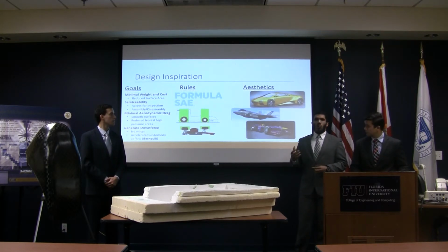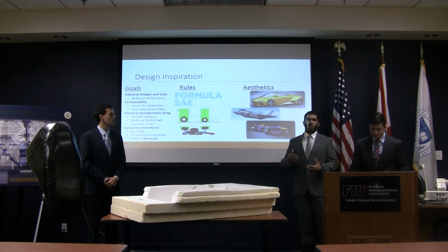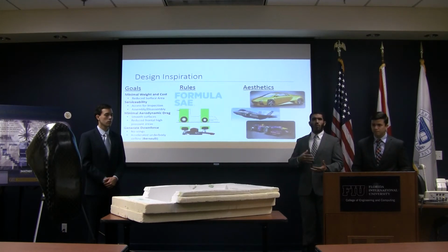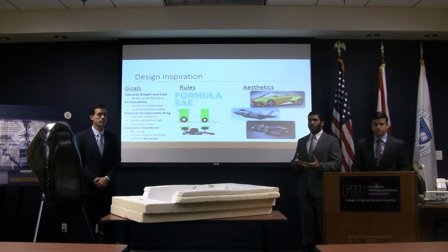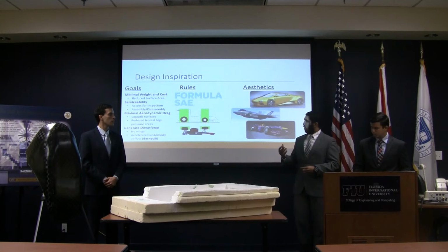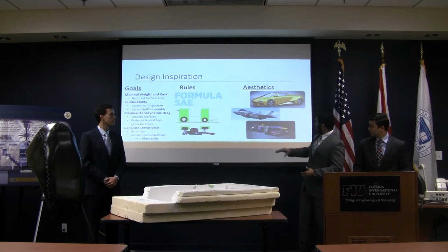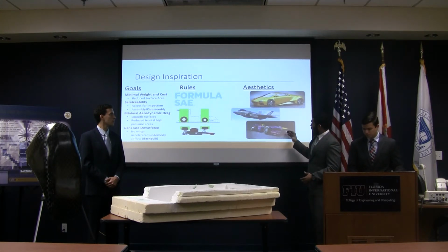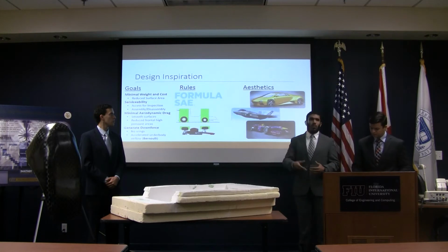And even though our car would not reach speeds where any significant downforce would be created by the body itself, we did use some downforce generating concepts to inspire our design. Mainly that would be the high nose of the Formula Ones, which serves to scoop air under the car, accelerating it. And by Bernoulli's principle, the acceleration of the air creates a low pressure area under the car, bringing it down.